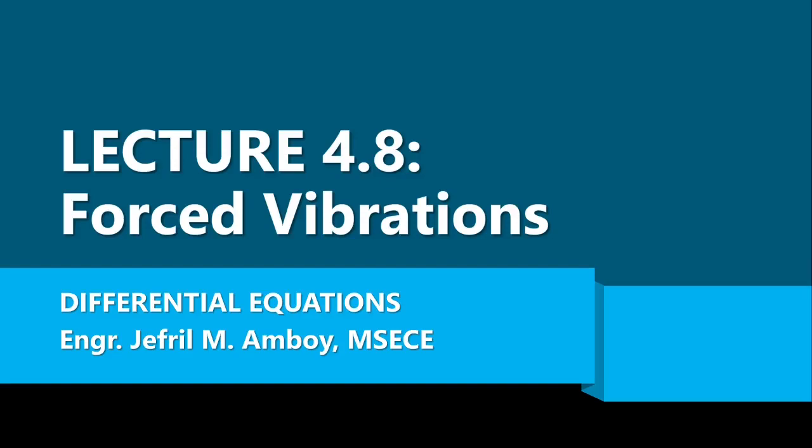Hi, in this video, you will learn how to obtain the response of a vibrating mechanical system with an input force. This type of motion is called forced vibration because the input serves as the forcing function or the excitation. Unlike the previous topic in which we solved homogeneous differential equation to get the free response, in this topic, we will solve non-homogeneous linear equations with constant coefficients.